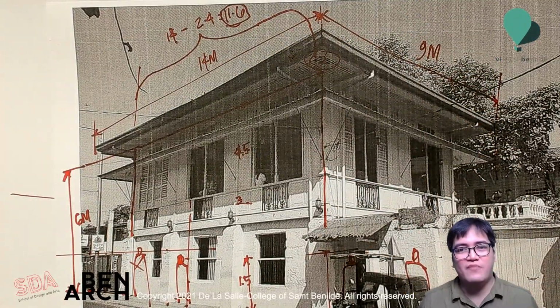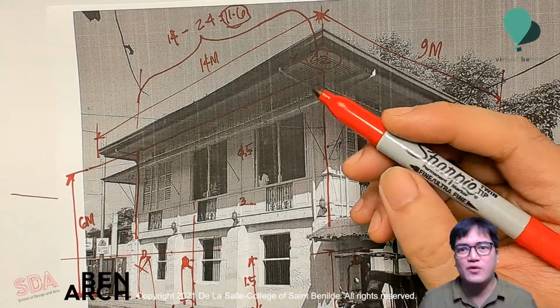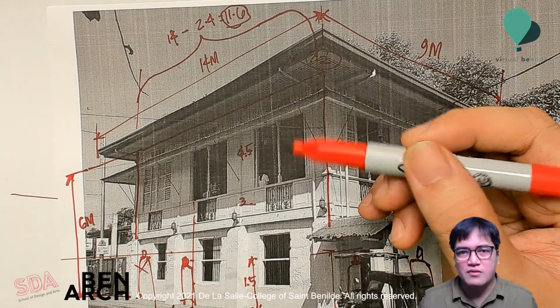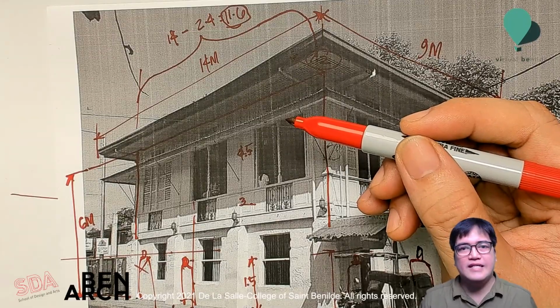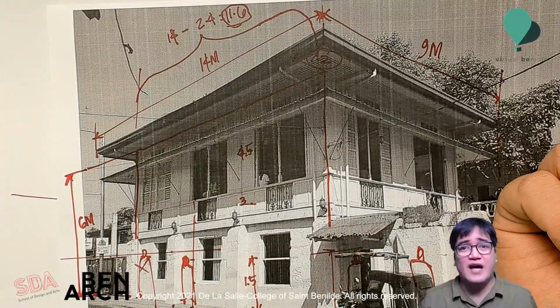To determine the width, I have to guess the relative measurement with an established eye level of 1.5 meters. You can get cues from vehicles or heights of doors and window sills. Window sills would be like 0.9 to 1 meter. Doors can be roughly about 2 meters. So the eye level would therefore be something like 3/4 of the height of a door.